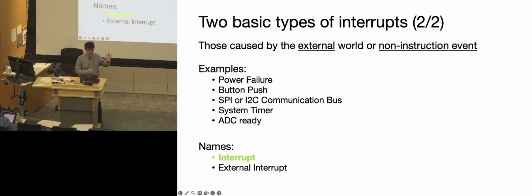And you can say that it's kind of a good interrupt because it gives you some events or flags to do something and to make sure the program acts as it's supposed to. So as we talked, like a button push and some of the communication protocols you will learn later, SPI, I2C, and also, for example, the ADC, analog to digital converter. Whenever that conversion is finished, it also gives a quick interrupt to let the system know, I'm ready, take the data from me, and then we can do some cool stuff together.